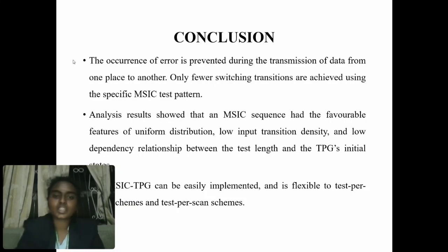Conclusion: the occurrence of error is prevented during the transmission of data from one place to another. Only fewer switching transitions are achieved using the specific MSIC test pattern. Analysis results showed that the MSIC sequence had favorable features of uniform distribution, low power transition density, and a low dependency relationship between the length and the TPG's initial state. The MSIC-TPG can be easily implemented and it is flexible to the test-per-clock scheme and test-per-scan scheme.